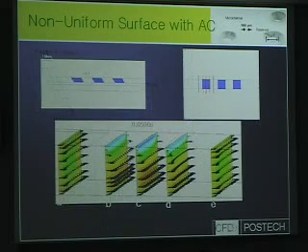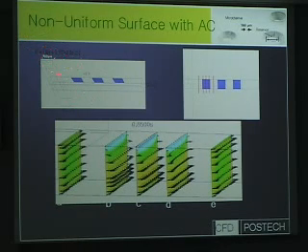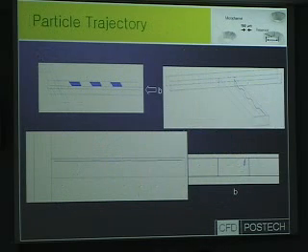Okay, same thing. And when we modulate as a function of time like that, strength gets larger and gets smaller. However, in this situation, even though there is a circulating flow near the surface, overall, the particle trajectory is not very interesting because flow is just parallel to this channel. Okay, so in this situation, we do not have horizontal mixing, so overall mixing efficiency is not dramatic.